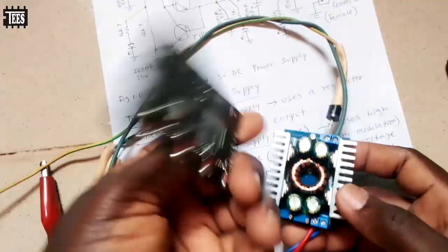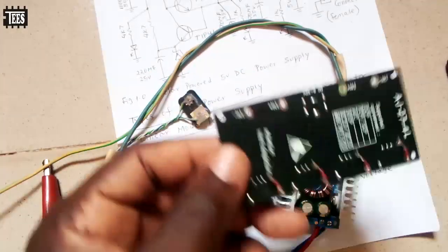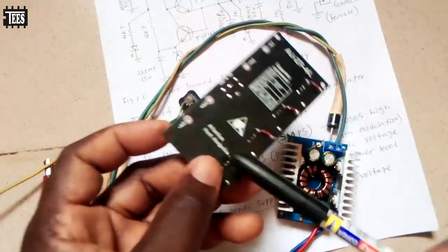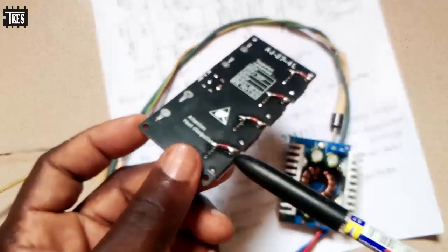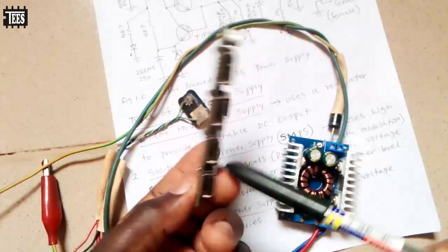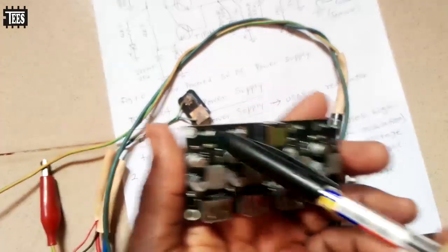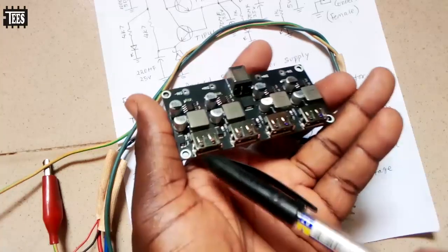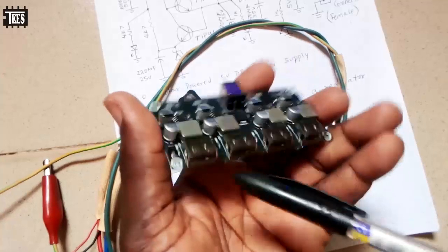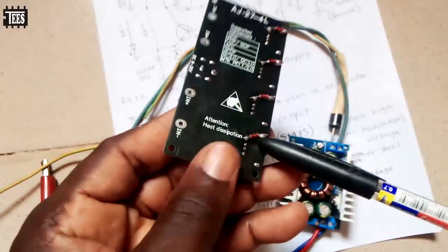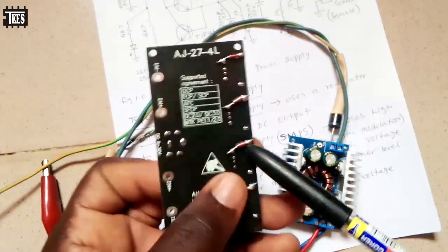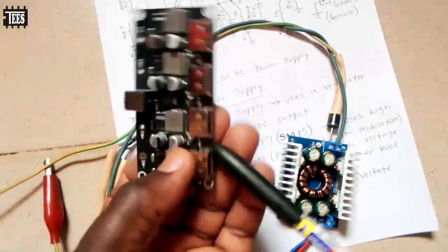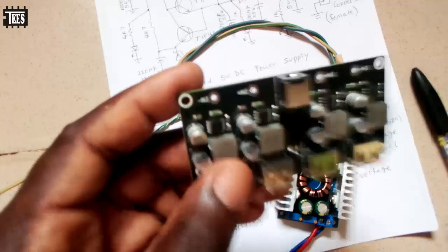If this thing is not available in the market, just like this one that I bought, I added these Zener diodes. This didn't come with protection, so it's very important. I had to put 5.1 volt Zener diodes on each of the outputs. There are 4 circuits here, like 4-in-1, 4 different channels each controlling their own output, not just one. So if you are buying stuff like this, make sure you put a 5.1 volt, 1 watt Zener diode, so that in case something goes bad, your phone will be protected.